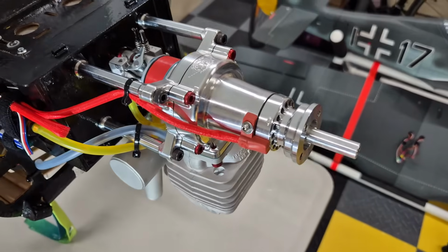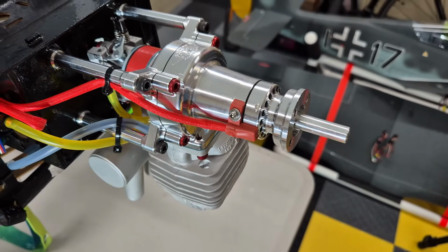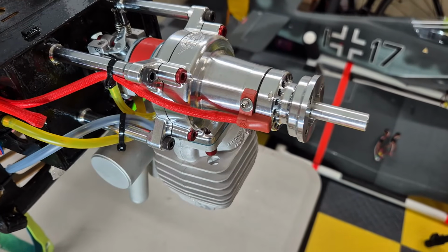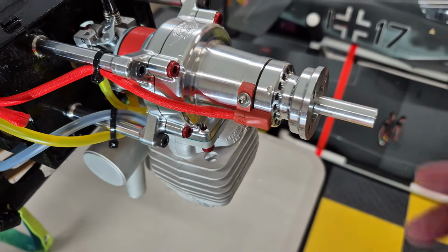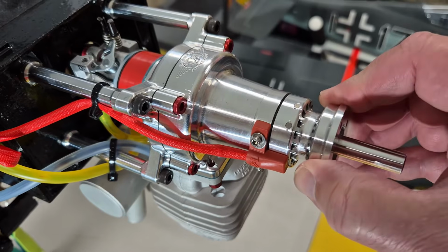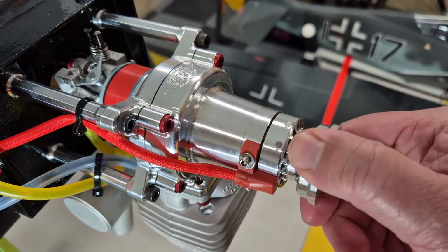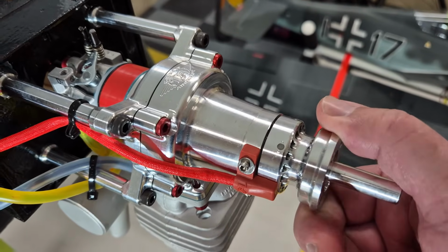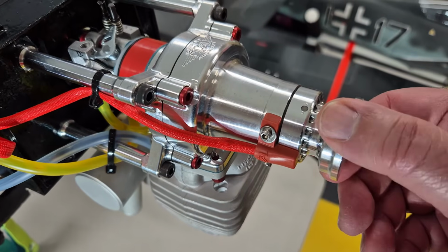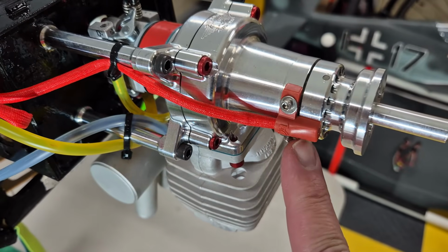So this is my little DA 35cc 2-stroke petrol, or as the Americans say, gas motor. It has an electronic ignition. The ignition picks up the crankshaft speed or crankshaft rotation by using a couple of magnets on the prop hub. So there's one there, as I rotate it around, there's another 2 magnets there. So in total 3 magnets. This motor uses 3 magnets so it can determine the direction of rotation to make it safe to start. So basically it doesn't backfire when you're trying to start it. So it's actually quite safe to start with your hands. There's a Hall effect sensor mounted here which detects the magnets.